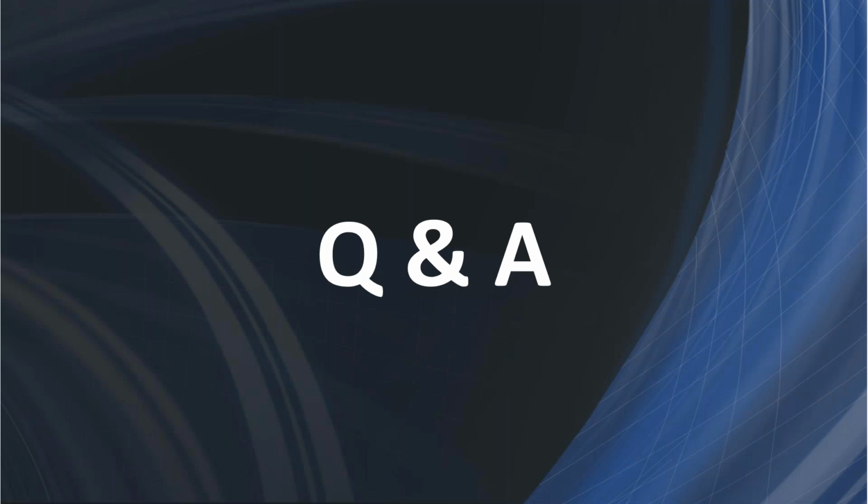So, questions. Some of the questions that were submitted had a common theme among a lot of them, but I'll just pull a few out of here. There was a question about jetting. Moldflow actually can predict jetting. There are special switches you have to turn on when you're doing a full 3D analysis to be able to predict that. And there are ways to reduce or eliminate the jetting by how you gate the part and how you do the part design. But again, make sure you're doing this up front on very thick parts when you suspect jetting may occur.